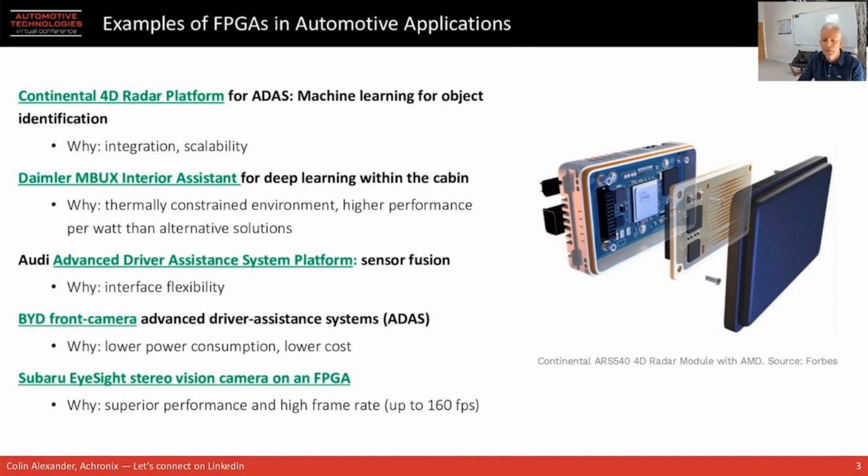This is a new technology that allows for the capture and processing of high resolution detail for object identification in any lighting or weather conditions and at higher speeds. 4D radar can determine and track an object's range, distance, azimuth, direction, or even elevation, as well as its relative speed, whereas previous generation radar could only determine speed and azimuth.